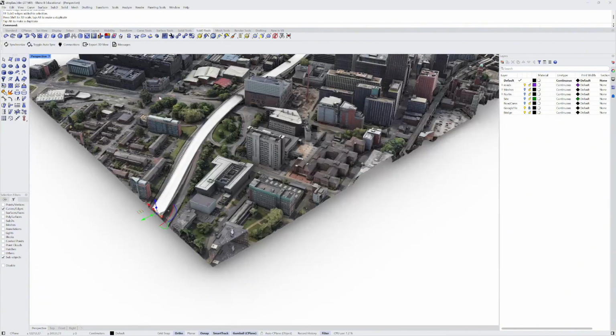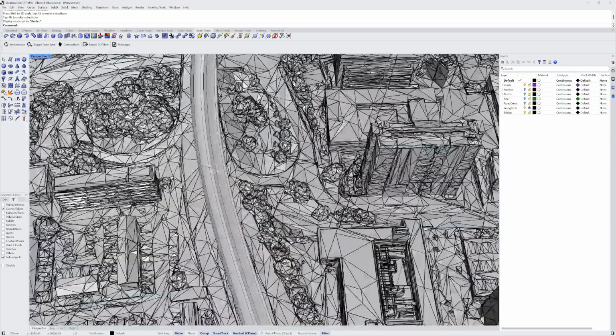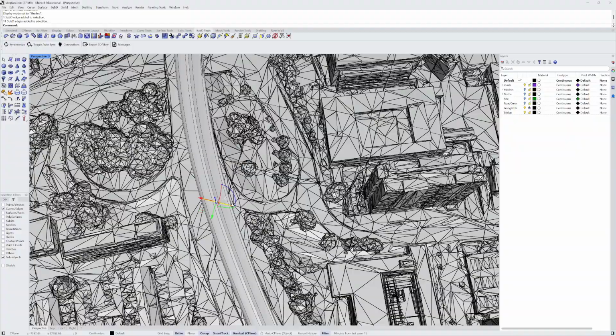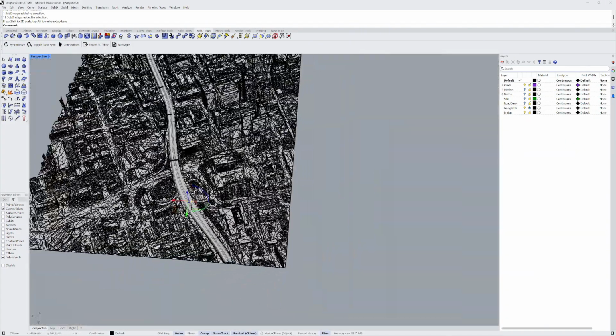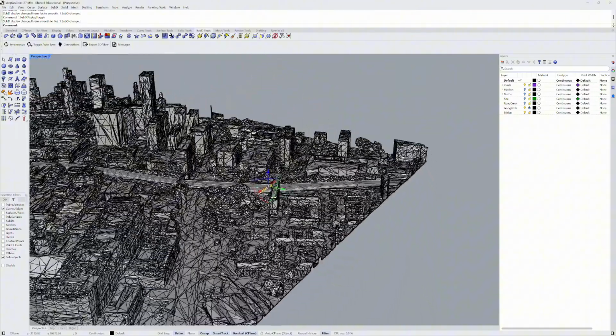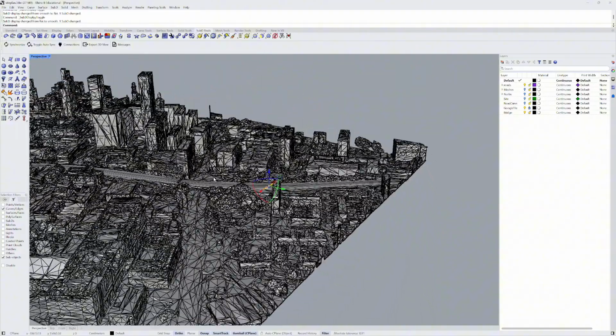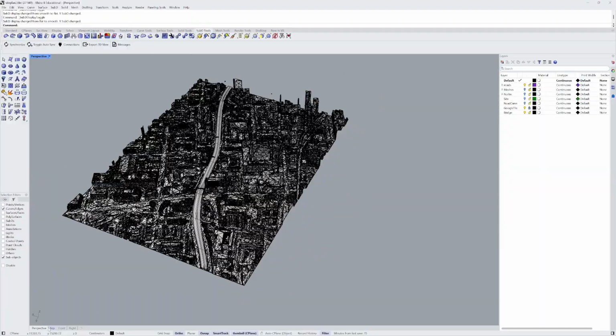And we can even turn on, if I just go back to shading mode for a second, we can select the edges that we've already created, and we can scale those if the carriageway goes wider in certain areas. And we could just start to build up our model in this way. So if I hold tab and tab again, I can start to see I've created this nice profile.